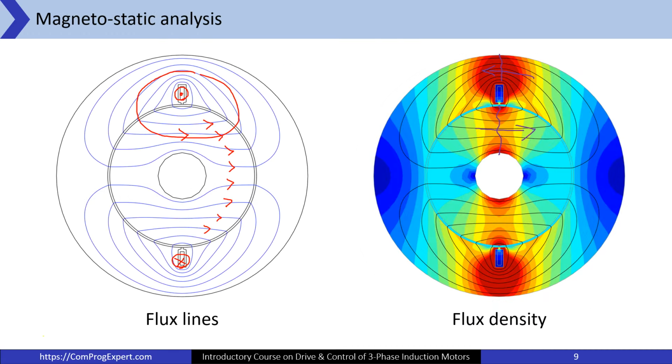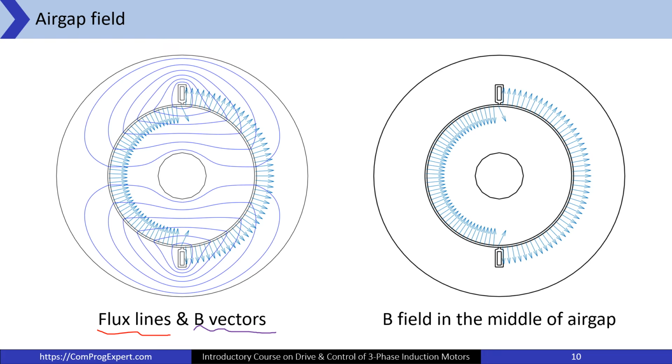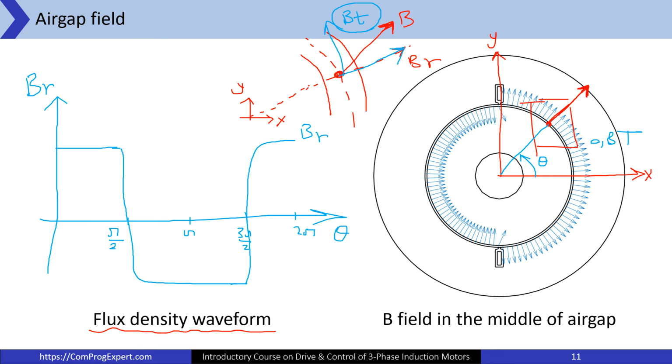Here in this case, I have only one coil, and consequently we will have a rectangular waveform that is not good. As you know, for this waveform we have high amplitudes for higher harmonics, but the fundamental harmonic is important for us to generate a good average torque.